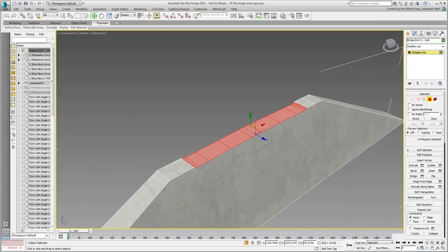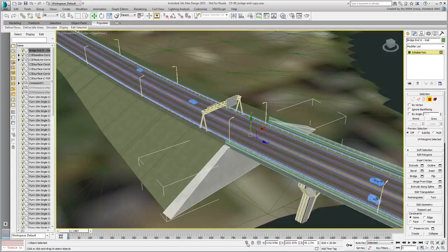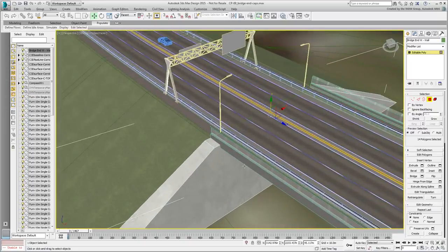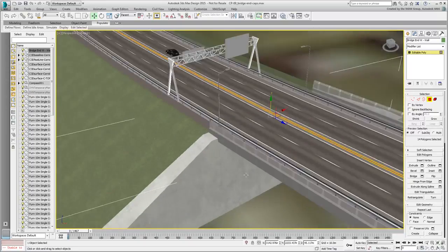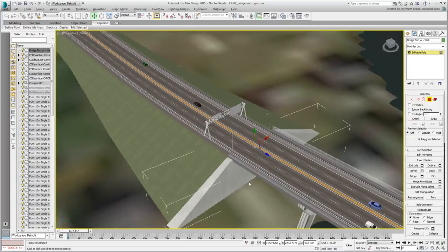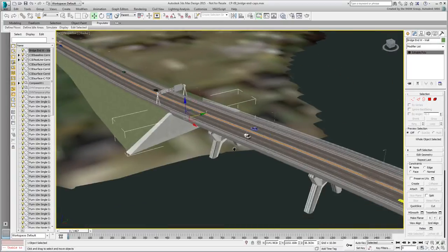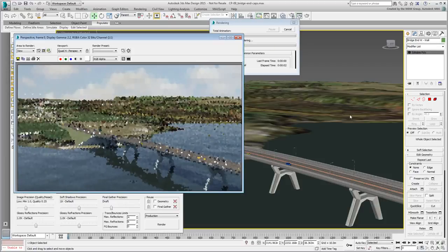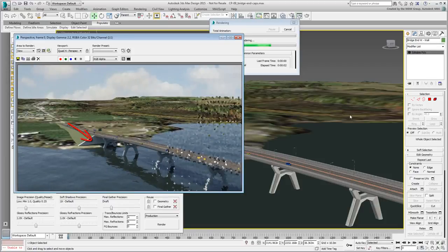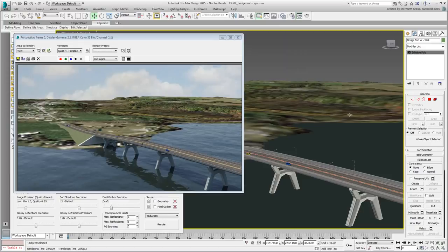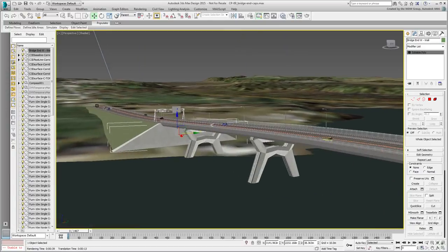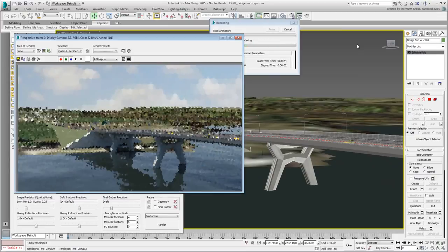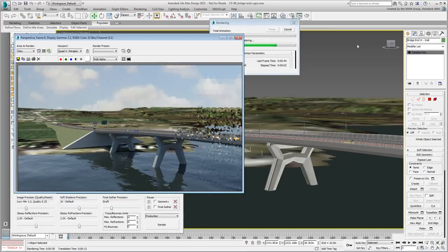You only need to bring the selected polygons down about 5 centimeters. Once you have exited isolate mode, verify no more flicker is taking place. Test render the scene and verify there are no more gaps under the bridge, not on this shore anyway. You still need to repeat the procedure on the other side of the bridge. It is exactly the same procedure, so consider it your homework. In the next movie, you go back to experimenting in Civil View by adding buildings in the background.